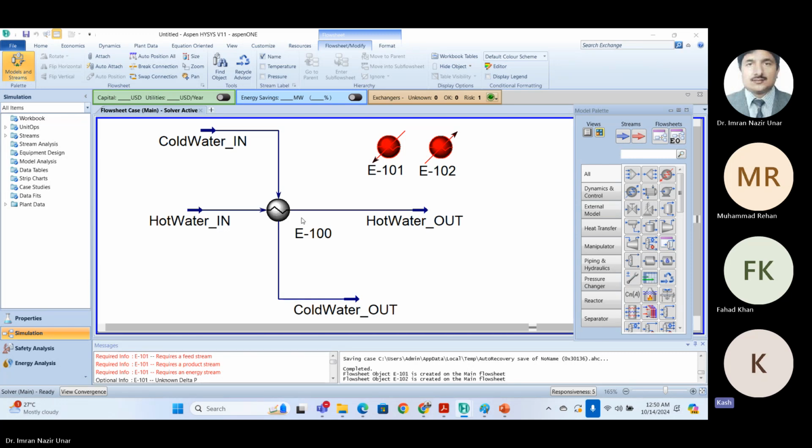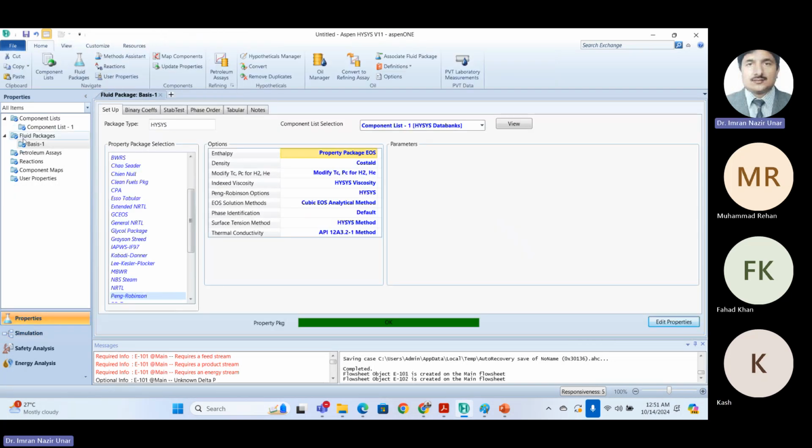Okay, about the pure components. Sorry? About the pure components, with this HYSYS, for example, I'm looking for ethylene. I search ethylene in the simulation names, and there are 3 or 4 ethylenes there. So how do I know which one to select? No, in a name you can recognize by their formula.